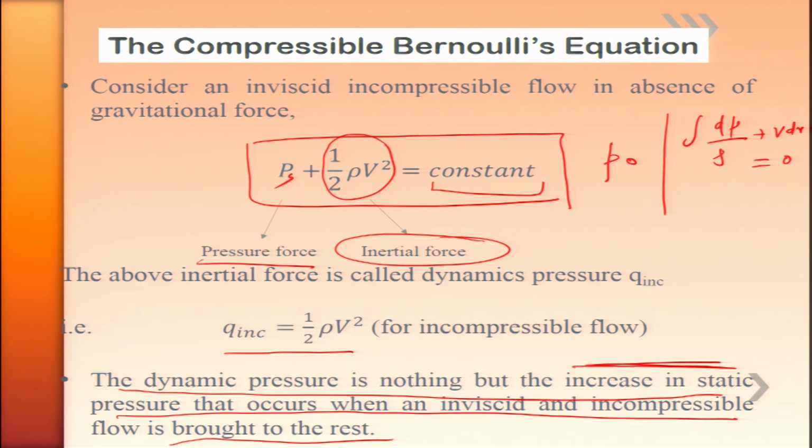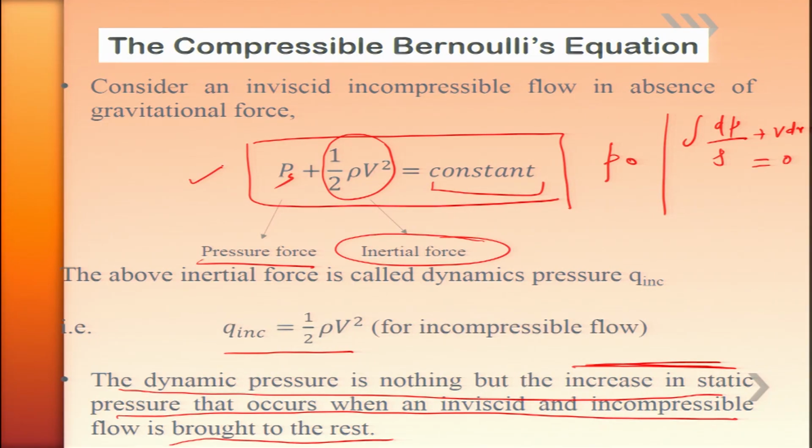Whereas in compressible flow, as we keep discussing, the kinetic energy is very high compared to the heat content of the flow medium. Therefore, a slight variation in kinetic energy leads to a large difference between static and stagnation conditions. That means this Bernoulli's equation form is essentially not valid for a compressible flow. Then what could that form be?